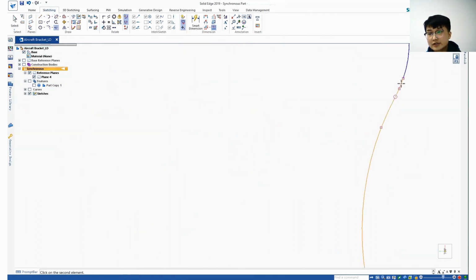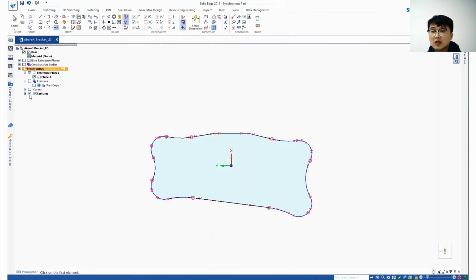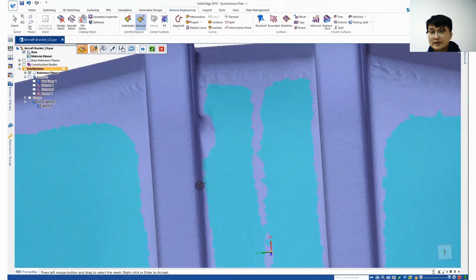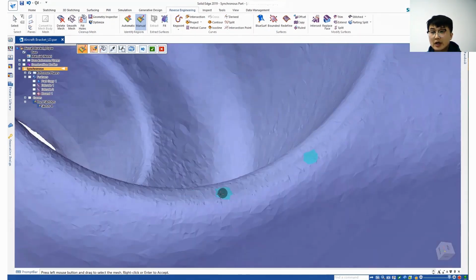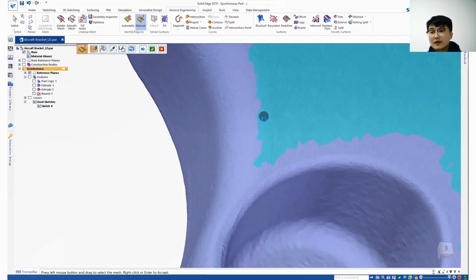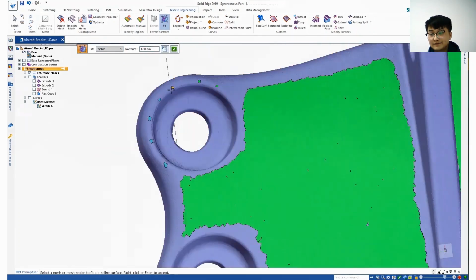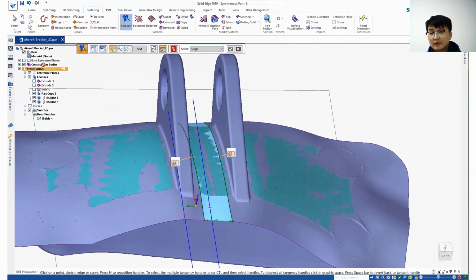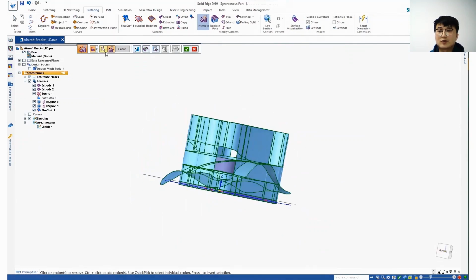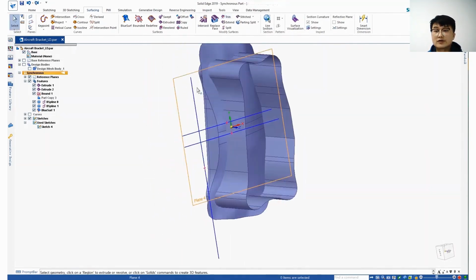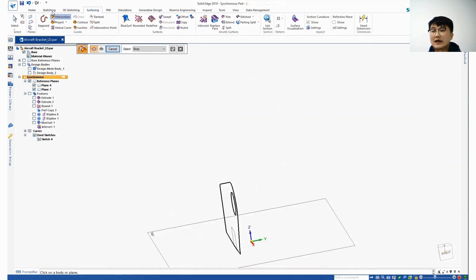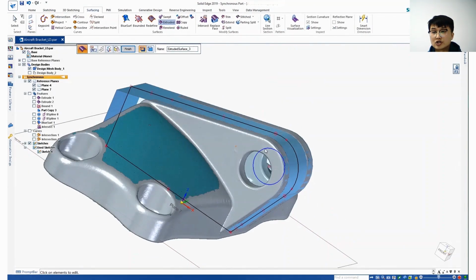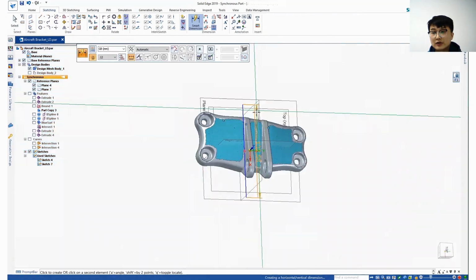We do the drawings according to the shape and the contour of the model. Then we got those surfaces. For those free surfaces, we identify those regions and fit the proper surface on them. As in the same process before, you just need to trim those surfaces and stitch them together so that you can get your entity here. For some parts, you need to draw the contour according to its shape and extrude the 3D model from the drawing.